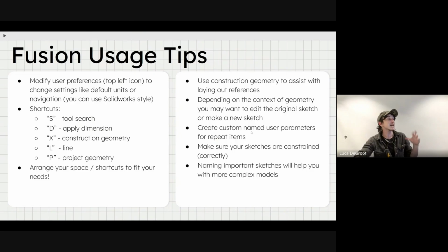Also, maintenance things like using parameters or naming certain sketches can be really helpful. You don't need to name every sketch. I do not really ask students to name every sketch. It matters when you're working with other people, because then you want people to be able to find which sketch does what. And it matters if you're going to be going back and forth between that sketch. Some sketches become master plans that I base most things off of. And then other ones are just a little geometry that I'm maybe using just to measure something. So some sketches will have more importance than others, and the important ones often are worth naming.